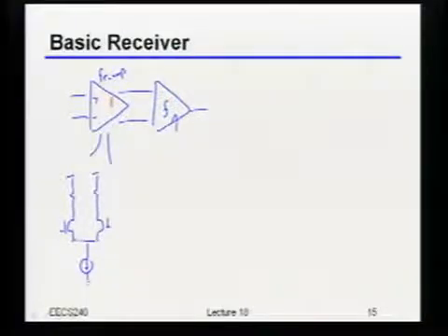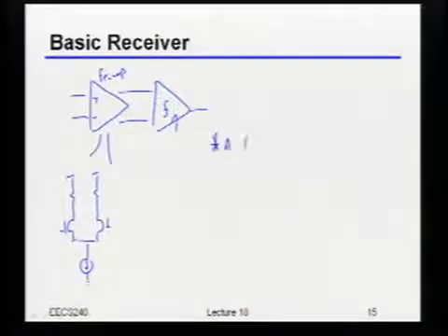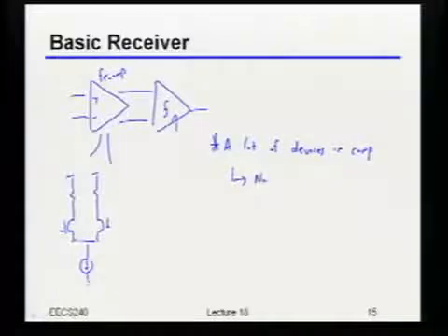Well, we'll see when you build comparators, they tend to have a lot of devices. Having a lot of devices tends to mean you have a lot of noise, and we'll also see later, you also tend to have a lot of offset.